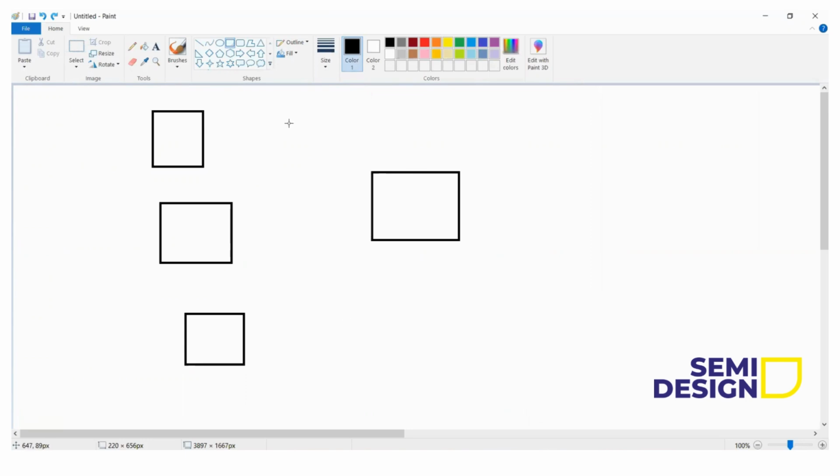Round robin means first this one. Let you start from here. You can start with any master. FIFO means whichever master is first, that master will be given access. Round robin means you can prioritize. Let you want to start from here, so first this master is given, then this master, then this master. Let you want to start with this master, you can. First this master will communicate with this slave, then this master, then this master. So arbitration means you are selecting which master is going to communicate with the slave, and the decoder circuit is used to select which slave the master is going to communicate with.